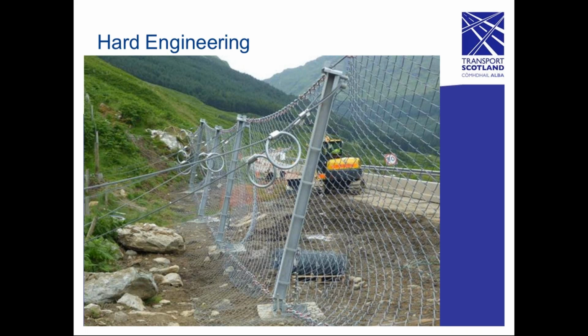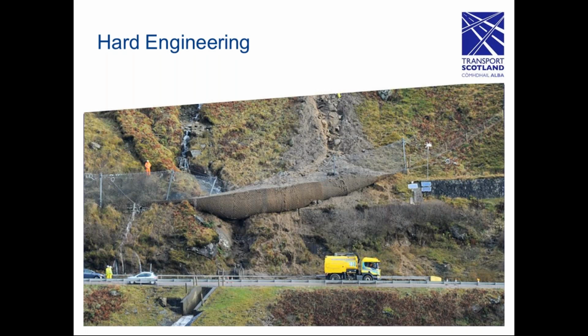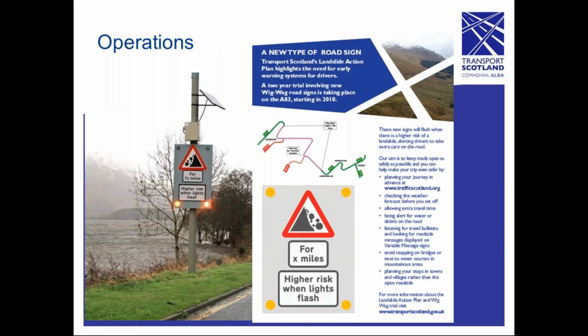Obviously, this has to be targeted, so there is a risk assessment process involved in positioning these, but the things like the landslide barriers do work. However, from a management point of view, it is awkward because you've then got to close the road to empty the debris out of the landslide barrier. We are now turning towards a slightly different approach in that we're using patch pits, which are less visually intrusive and are easier to manage when they do become full. And we're also looking at other engineering approaches, soft engineering like planting as a potential mitigation hazard.